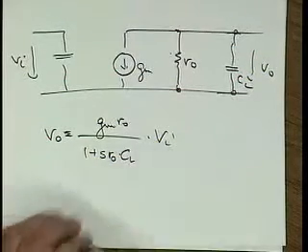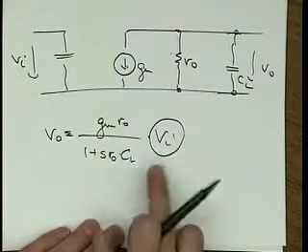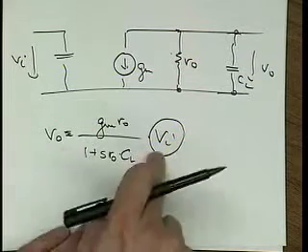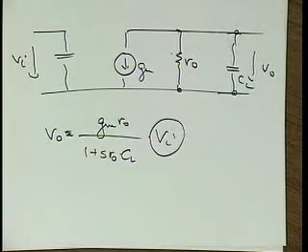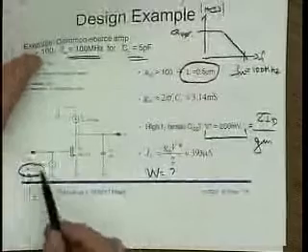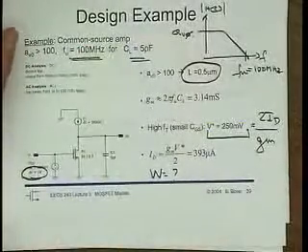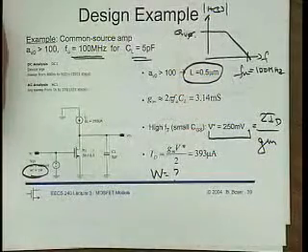Times Vi, of course. Now you can put any Vi you want into this equation. You always get a Vout that is just larger than Vi by the gain of the circuit. It doesn't matter at all what this Vi was once you are in the small signal domain. You have to be very, very careful. I messed it up now, but there is also a DC equal whatever, a few hundred millivolts. That's the DC bias point.